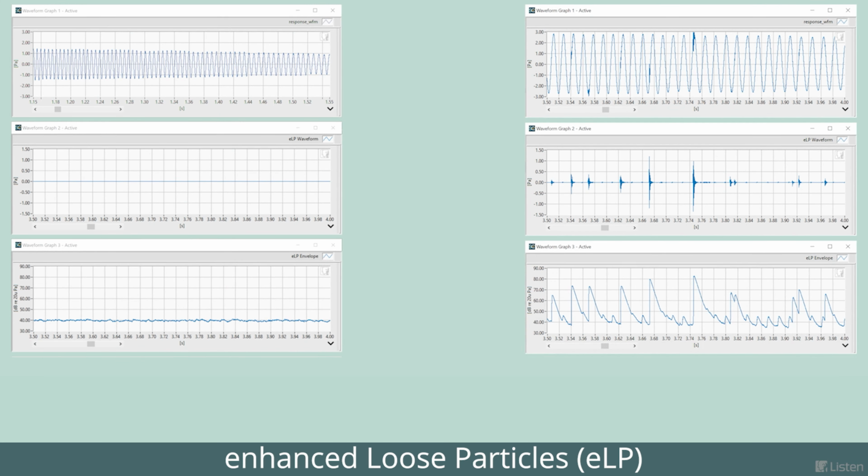Next, we apply an envelope analysis to get a time domain measurement. You can see the energy in the recorded waveform plotted against time. You can see the transient defects as random bursts of energy. You don't see these on the good speaker.